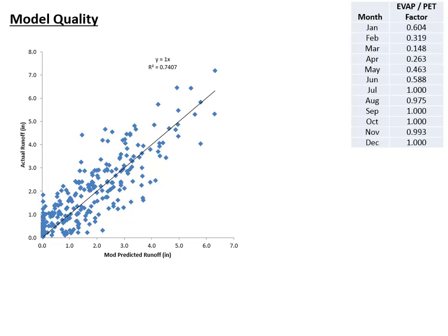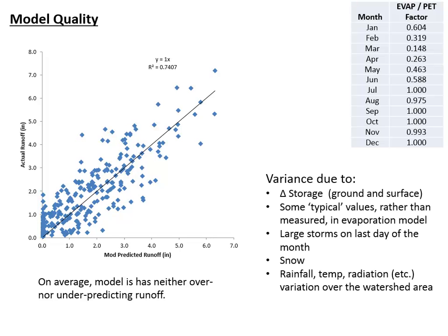There are models that have been published in the literature that have an R² of about 0.6. And there's lots of variation here that the model doesn't take into account. The reason why that isn't a straight line is that there are some months where there isn't any precipitation, but there's still going to be runoff because of base flow, because of groundwater moving out of a watershed and providing the moisture.